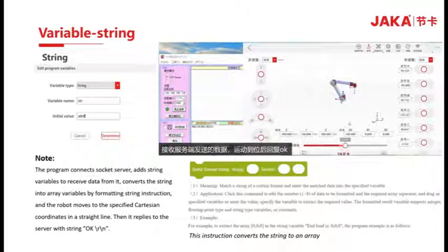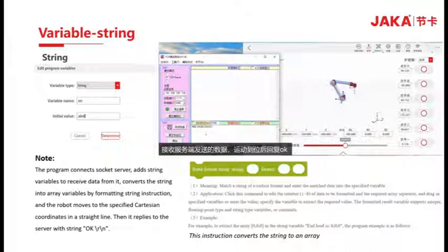When the program is launched, we just need to send the robot the new coordinate. Here will be the Z position. So the robot will simply move along the Z axis. We see the behavior of the robot. He moves and then send OK. We don't need to relaunch the program every time. The program is optimized to be used without touching it.